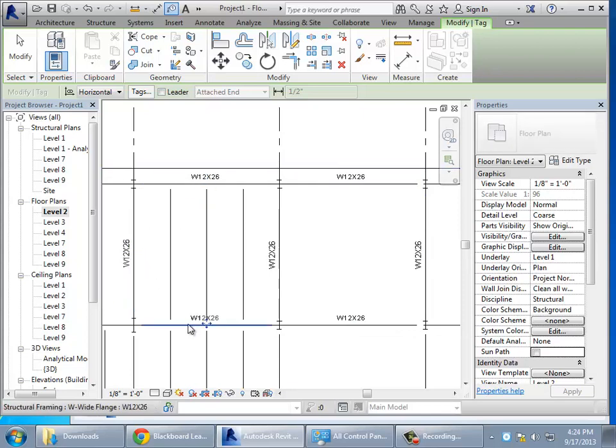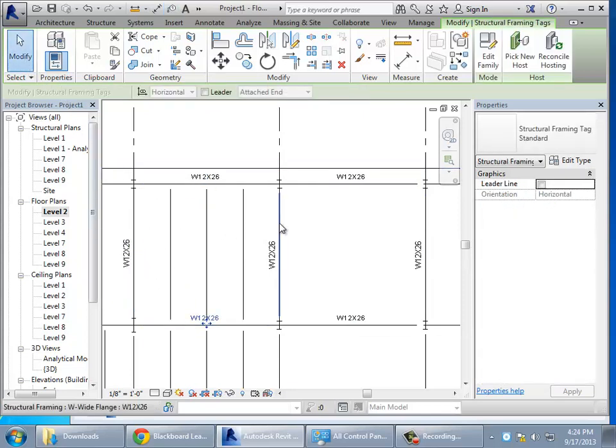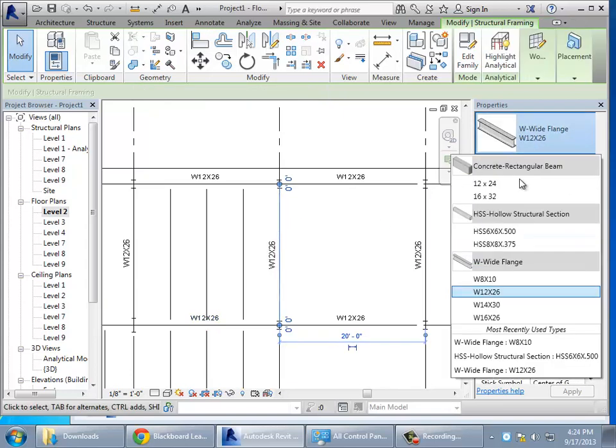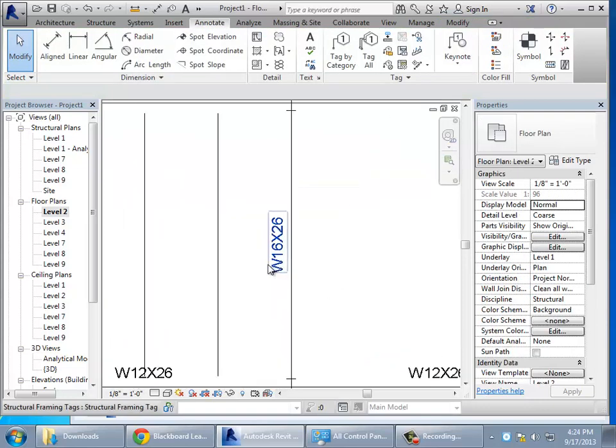And the nice thing about doing it this way, as I put those in there, is if I go through and choose that element, and either the structural engineer or some analysis program changes it, as I change it, not only is it reflecting accurately in the 3D modeling, we'll actually pull right back that and basically the construction document will stay current. Okay, so that's one of the huge values of doing building information modeling, is that there's no longer text which is severed from the actual meaning in the model. You're actually reporting the true value in the model. So hopefully leading to a lot less inaccuracy.